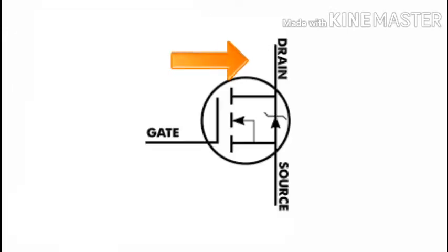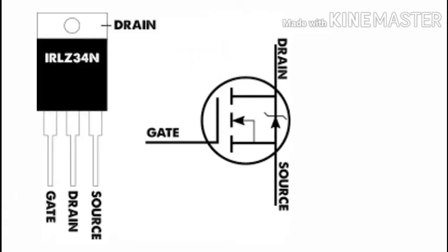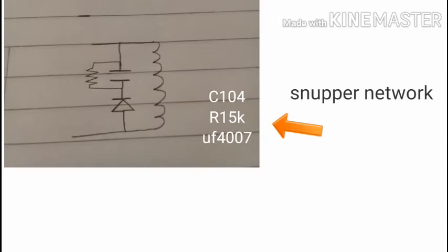Protection for the drain is necessary too. Most switching applications are for inductive loads, and all inductive loads create voltage spikes, which may damage the MOSFET. My advice is a snubber network or a simple diode across the inductive load.